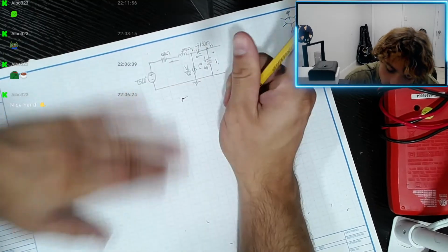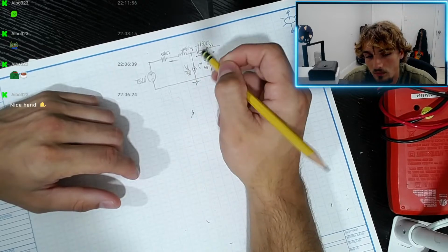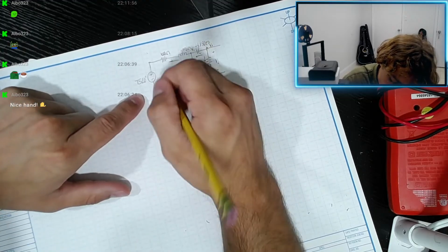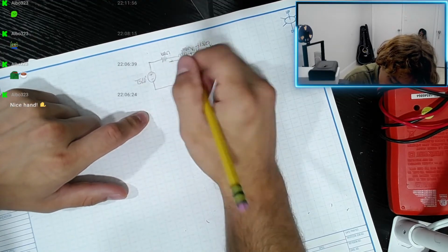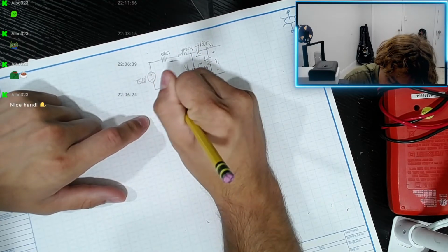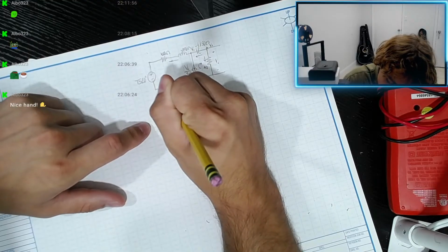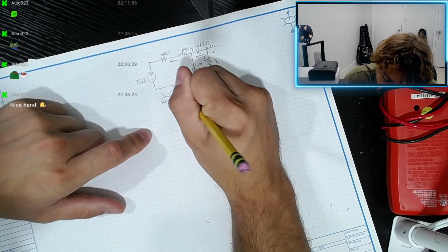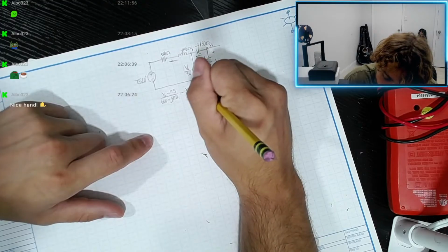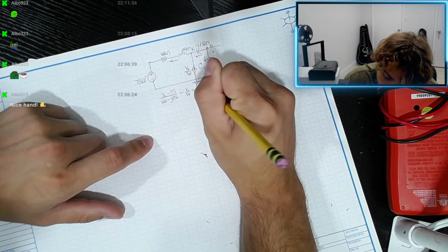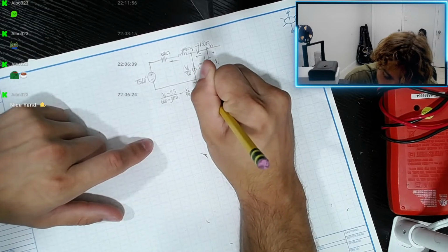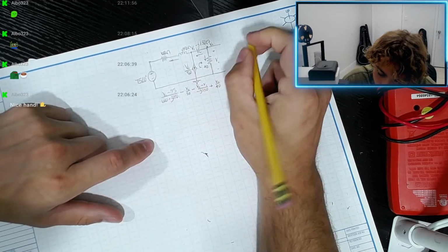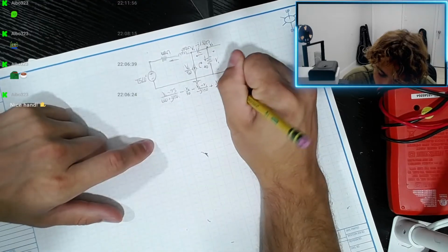So V1 minus 75 divided by 600 plus J150, minus V out over 50, minus V out minus V1 divided by negative J150, plus V out divided by 40 equals 0.